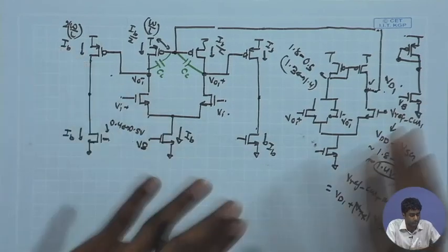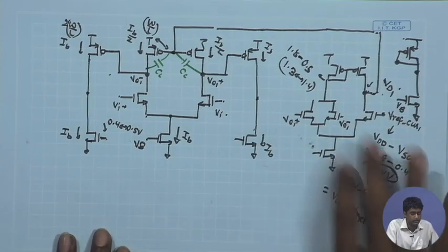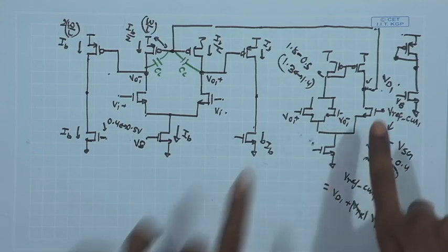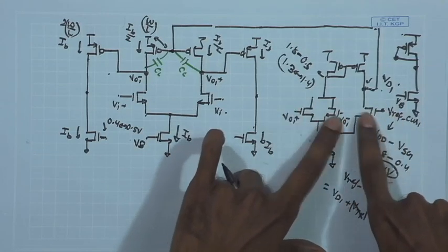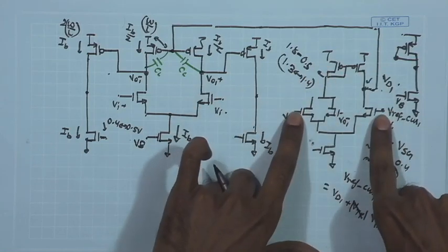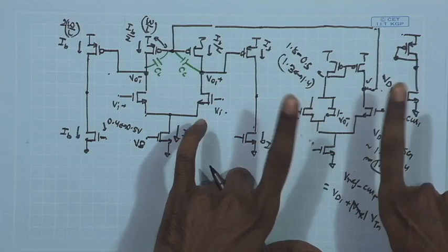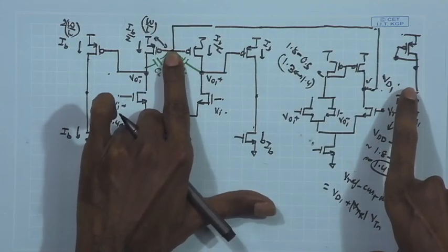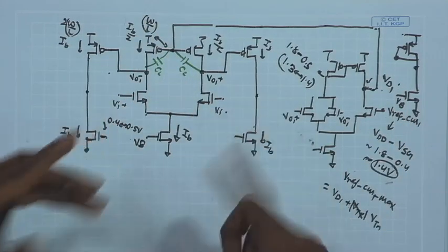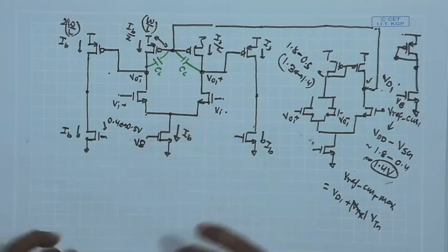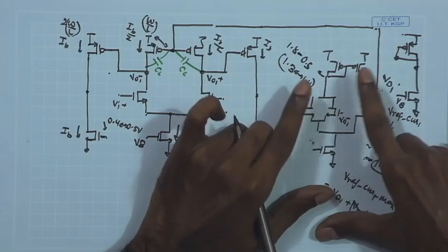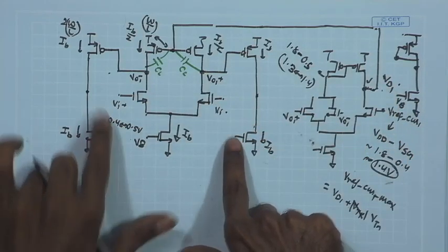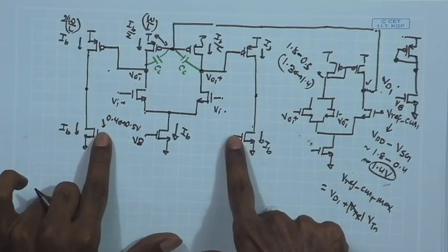And here we are discussing two separate common mode feedback loops and looking at some of the details related to biasing. Just like we concluded that this error amplifier with NMOS as input and PMOS as load is able to handle the required reference voltage, close to 1.4 volt, and is also able to provide an output voltage suitable for biasing this PMOS. Likewise, we also need to argue that a different flipped topology, with PMOS as input device and NMOS as load device, will be required if we are constructing another common mode feedback loop for biasing these two.